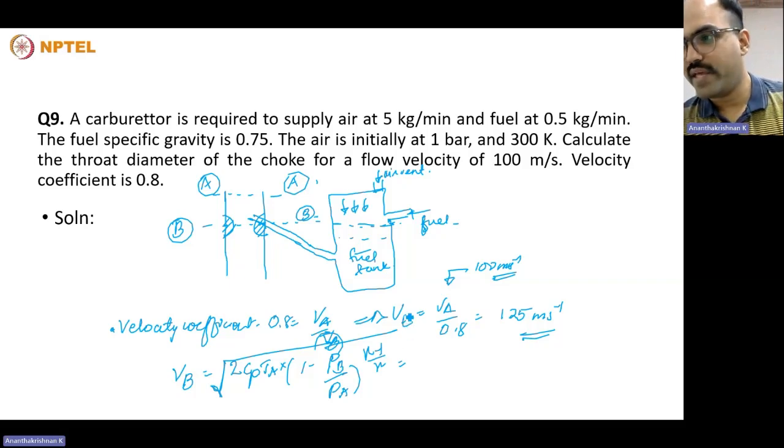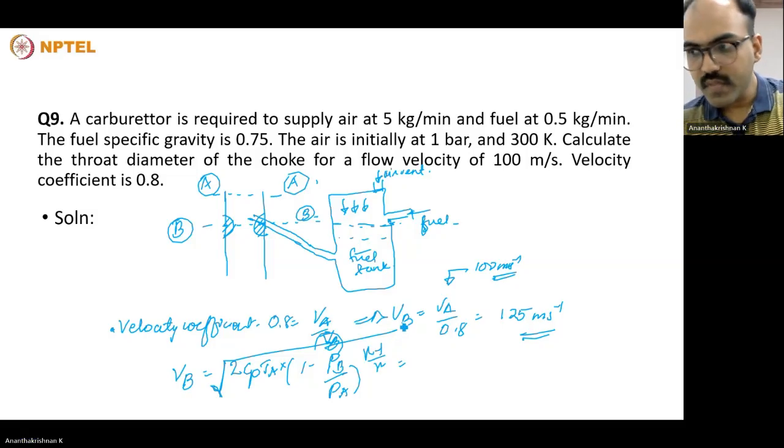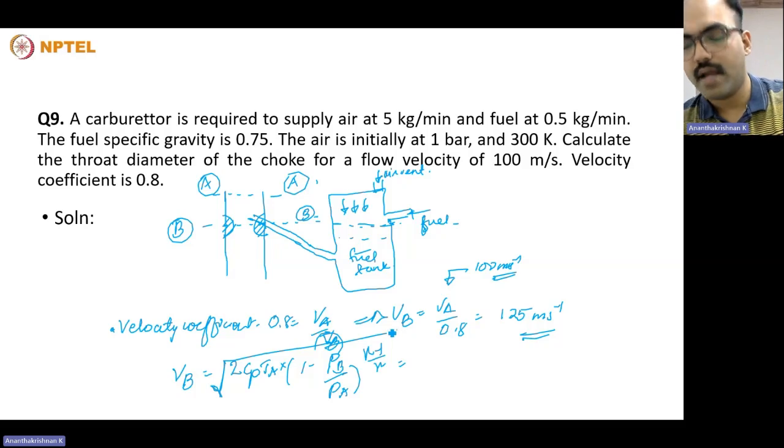So what we can consider between point A and point B is that it is not actually exchanging heat with the surroundings. We can consider this to be an adiabatic case. So at point A and point B, the state points of pressure and volume follow the ideal gas and adiabatic equation. For the time being we are neglecting whether this is isentropic or non-isentropic.